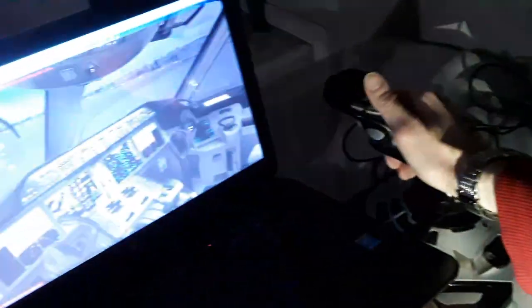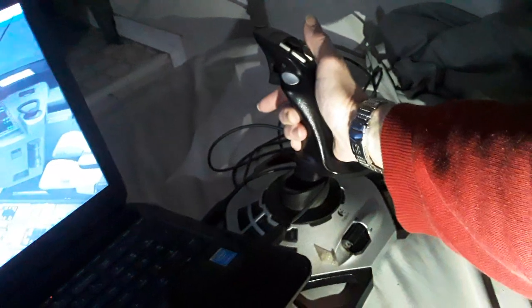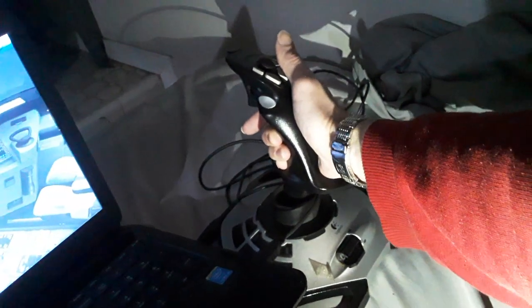It trims automatically itself. Also for the autopilot flight director system panel function, we can also trim manually, or we can override by cutting off these red guarded switches. So like in the Airbus aircraft, when we climb or descend the aircraft or make left and right turns, the flight control computers will limit the aircraft and will balance it in terms of G acceleration, where G is the Earth's gravity. So we can make left turns in the Airbus 67 degrees full side deflection, or 2.8 G, right deflection the same, 2.8 G or 67 degrees.